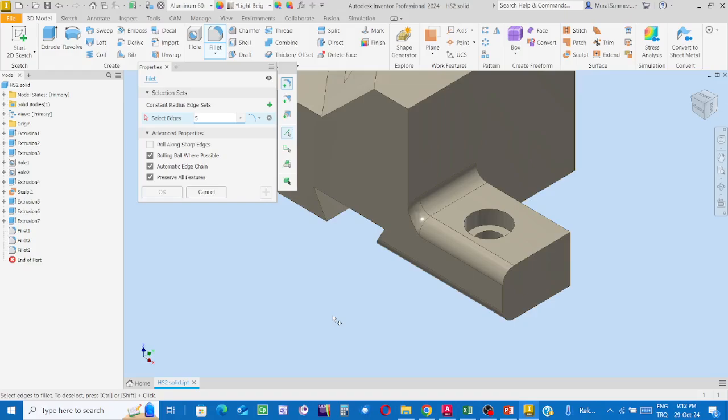Well, by rounding an interior edge, we prevent having excessive, very great stress values within the body, and via this we can prevent the weakness. Okay, sharp edges cause the weakness. If you round the sharp interior edges, this means we achieve to prevent failure. The body will be stronger along the edge. Well, a rounded exterior edge is called round. A rounded interior edge is called fillet.